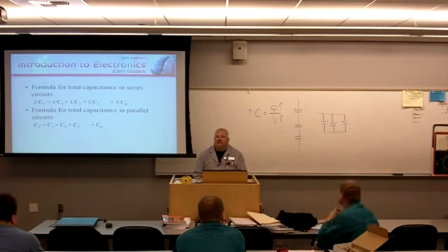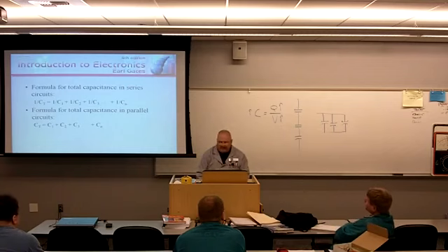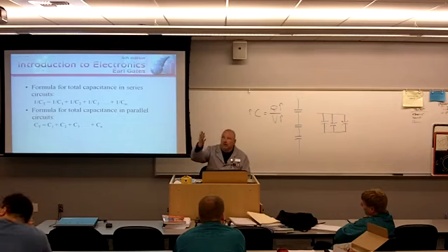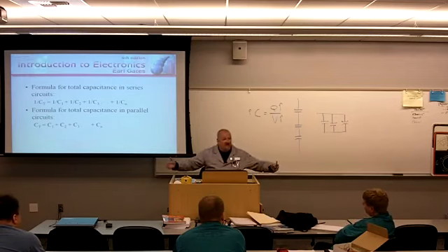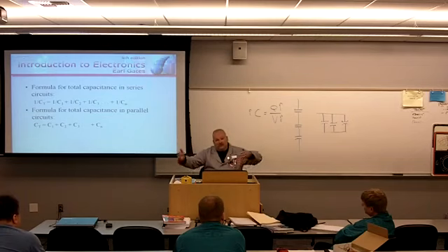So I don't know if that helps you, but it helps me remember formulas if I understand how the formula works. If I just give you a formula, C is equal to Q over V, okay, I'll remember that. That's not going to do you any good. If you remember C is equal to Q over V, increase the area of the plates, I could store more Q, Q goes up, C goes up. Distance between the plates increases, V goes up, C goes down, inverse proportional relationship. Make sense?